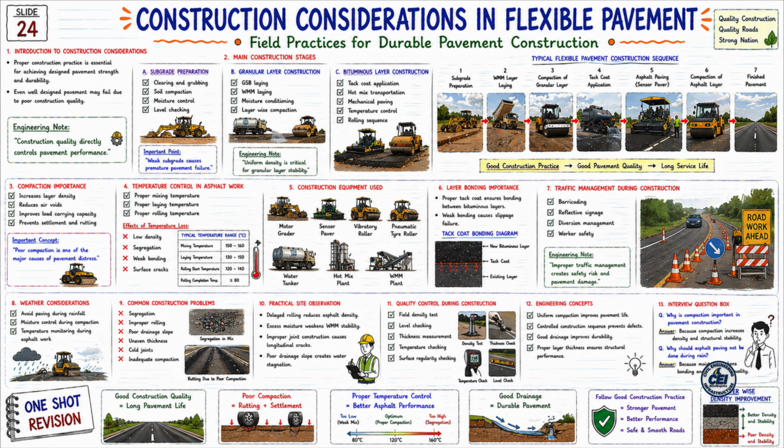Quality control during construction. What is checked in construction QC? Field density test. Level checking. Thickness measurement. Temperature checking. Surface regularity checking. And proper QC ensures durable pavement. Now let us look at the 12th topic.